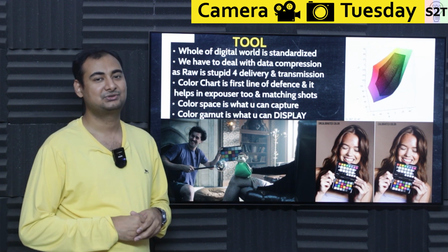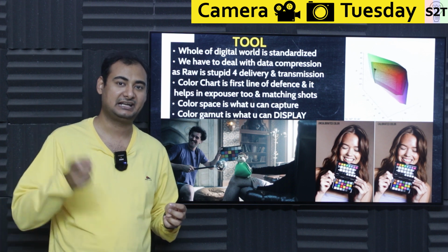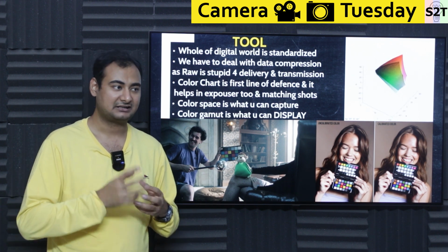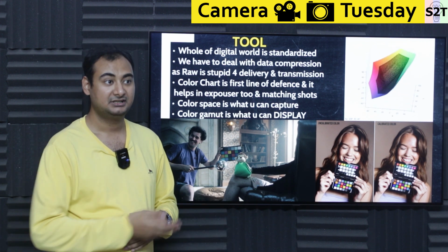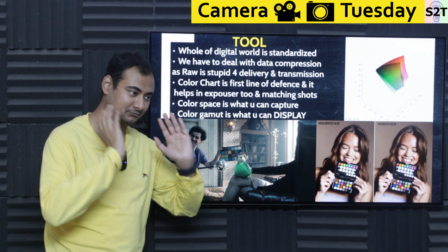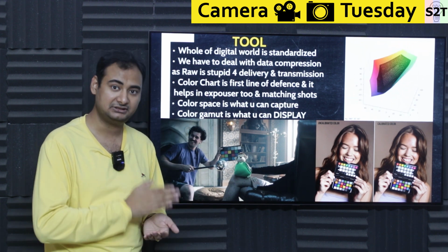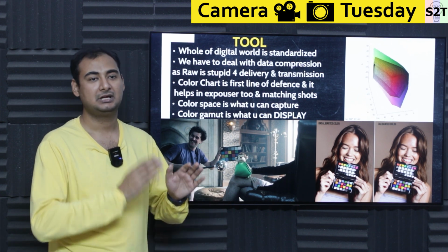There was a phase where we used actual 3 sensors. Be mindful, that's coming back, because for 8K live streaming of the Olympics and all that, you need 3 sensors. Bayer calculations are too slow to be done at 120 fps in real time continuously for hours on end. So just put 3 sensors. And for industrial use, like machine vision, they still use this technology. It's a very awesome and the cheapest technology to give you absolute color.